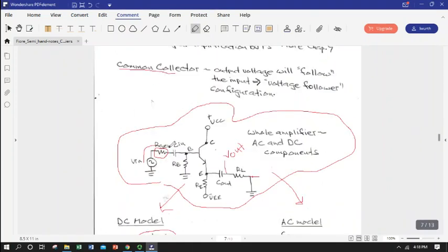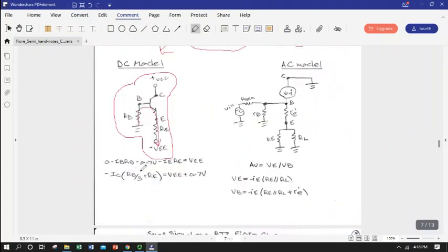We're also going to use the beta for the transistor, which we are assuming is, generally speaking, you can assume is 100 unless it's otherwise specified. That's a pretty good round number that's common for many BJT devices. Okay, so basically here's our setup that's going to give us I sub C, and I sub C, when we solve for it, is going to be used to define our R little e.